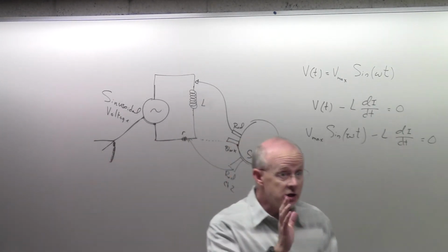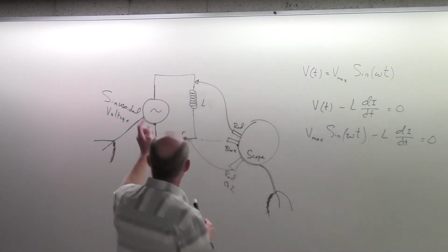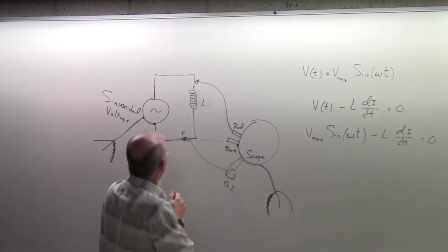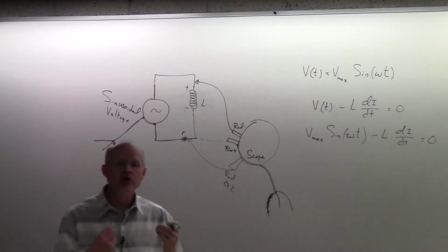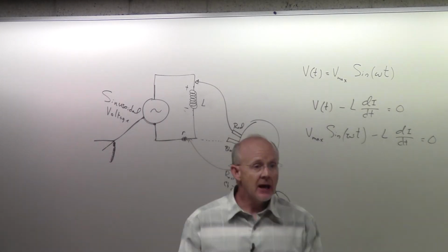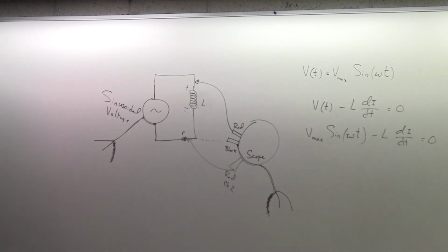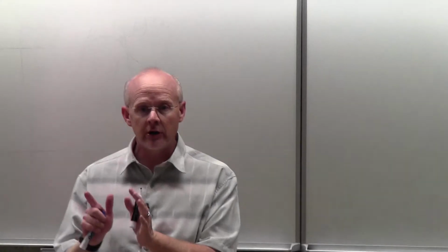Remember what we said, that when the voltage is trying to shove current through the inductor, during that moment in time, there would be an induced EMF. And so I want you to see here that this is not just going to be an infinite amount of current. There is an opposition to the current flowing.